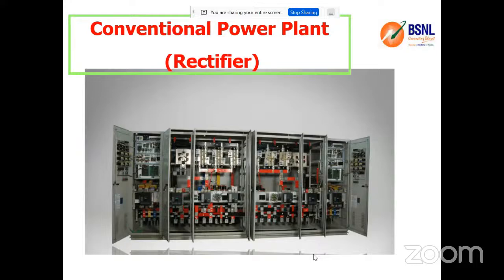Suppose today I may be using one module for a few loads, but tomorrow I may need more equipment or there may be more demand on the load. The same power plant could not be flexibly added to, increased or decreased based on my load requirement. That is also one of the difficulties we faced with the rectifier. It is always available with the maximum size, so we cannot reduce it, nor can I increase the capacity of the plant. All these things are overcome with the latest technology called the SMPS power plant, that is, switch mode power plant.